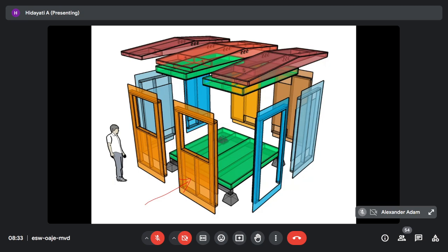So a wall panel you can also make at the factory. But the dimension you have to be careful about, because when we talk about IBS, the dimensions of the elements must follow the modular coordination, meaning the standardized dimension, for IBS. In terms of dimension, we will discuss that after this.